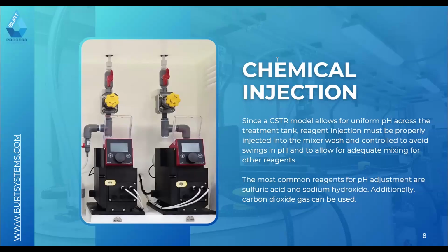Now, most of the time when doing pH neutralization reactions, you are taking what's still considered a fairly dilute waste stream, even if you're at pH 1 or pH 13, for example. So you're not going to see things like thermal rise. You're not really looking at a chemical reactor system. When you have stronger waste streams, which is rare in the pharmaceutical industry, you tend to see it more in things like semiconductor, where they may have strong nitric or HF streams.